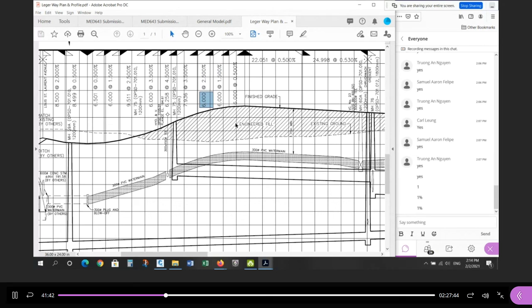6 meters, 1%. That's like a K value of 6. So they're approximating a vertical curve with a bunch of straight lines. So they avoid using a true parabola by using a bunch of short tangents at 6 meters long. Okay, so this is the same as a K value of 6. For the crest curve here and for the sag curve here, same thing, 6 meters, 1% change.